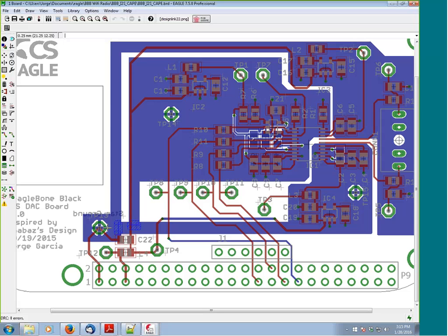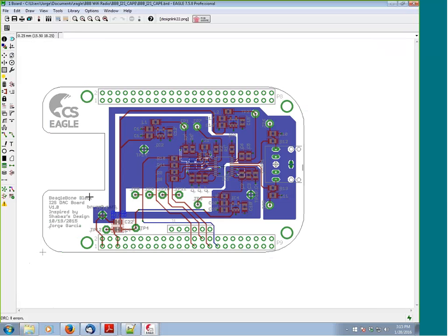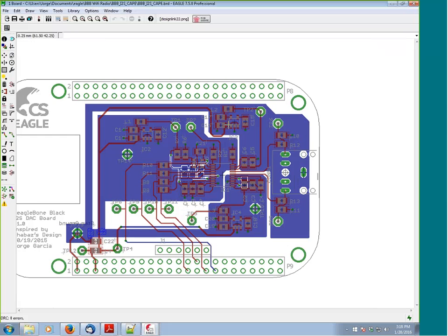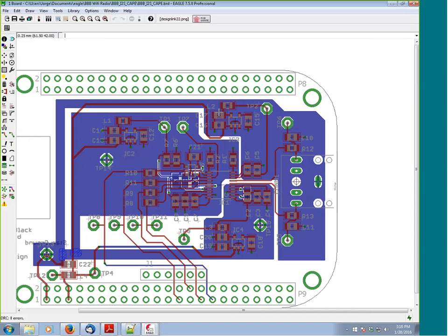I see. And then on the upper part, it's not really narrow, but it's pretty long from the ground plane to the top right corner. Wouldn't that be a little more resistive on the ground side? Isn't it better to have a wider ground? I don't know how much power that section is consuming, but I'm talking from the L2 all the way to that ground, which is more like an inverse L shape. Yeah, this part right here that I'm running over. That is correct. Okay, very good point.